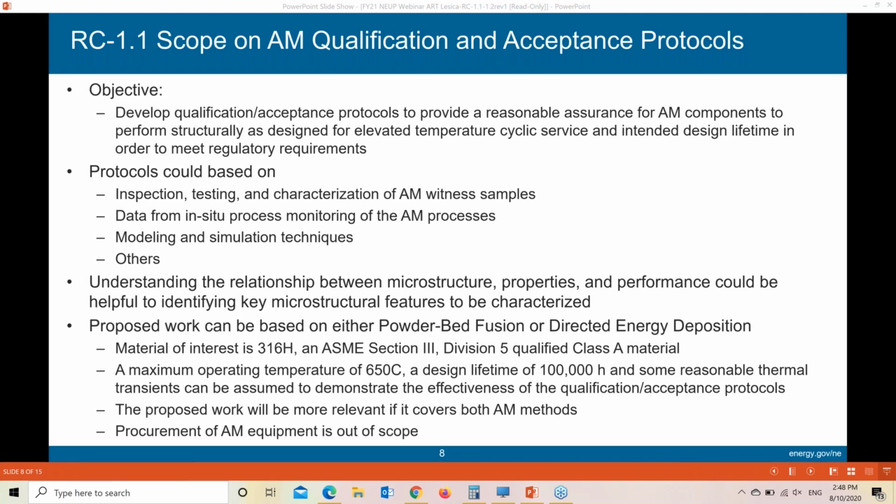Is the graphite irradiation study limited to structural graphite, or is graphite matrix used in HTGR fuel elements also under consideration? Great question. Let's focus on just the structural graphite for now. Matrix material, simply because it's not graphitized, does have a different irradiation performance, and so there may be differences in the starting mechanisms that change the microstructure. So let's start on just the structural graphite for now and leave the matrix to another day.